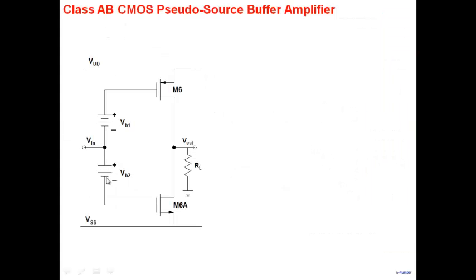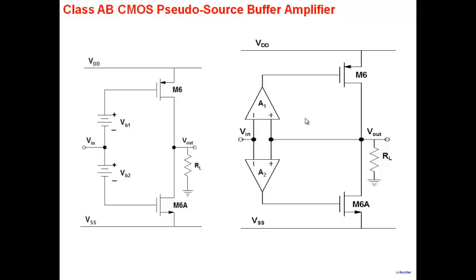This is the amplifier that we've been talking about. I'll stop after this. Class AB amplifier. One of the problems with this particular amplifier is that, while it has high efficiency and good swing, remember it's a common source amplifier and therefore its output resistance is large, right? So what one can do is, I've hinted earlier, one can build an amplifier like this here.